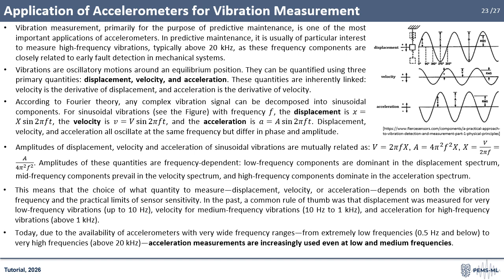The amplitudes of these quantities are frequency-dependent. In the displacement spectrum, low-frequency components are dominant. In the velocity spectrum, mid-frequency components prevail, while in the acceleration spectrum, high-frequency components dominate. This means the choice of what to measure, displacement, velocity, or acceleration, depends on vibration frequency and sensor sensitivity.